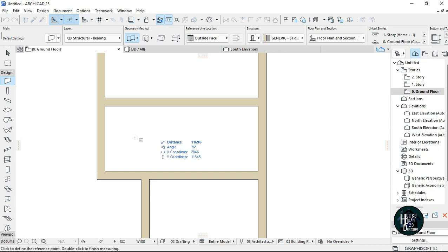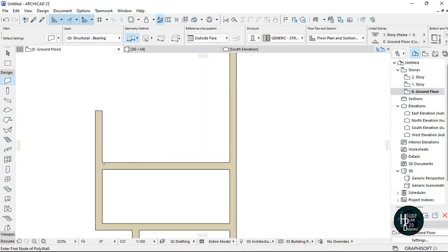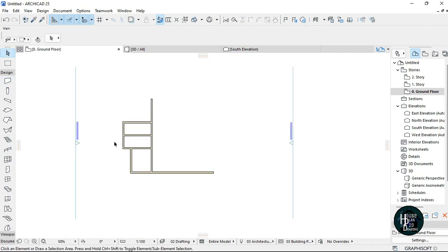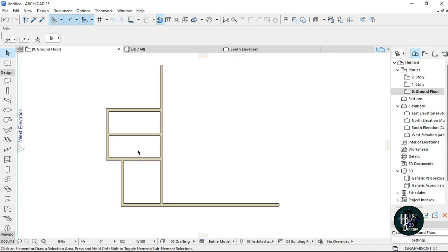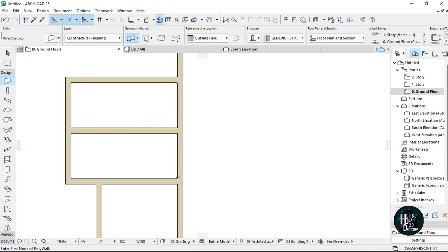Now you can press M to measure what you are doing, to show you're actually working accurately, which is 18. Okay, now I'm going to do the same for this other side. So now we have something like this. So I'm going to hold down Alt over there, then take this out, take this inside rather by 1000, and move this up.